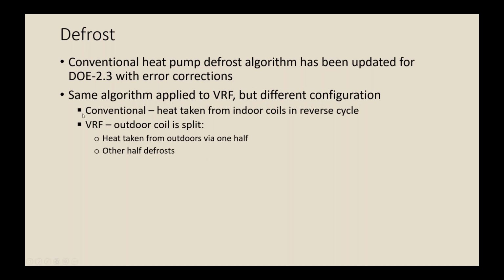In many of the larger, newer VRF systems, there's a configuration where the outdoor coil is split into two separate circuits, and the compressor can operate during defrost where it draws heat from one of the coils and rejects heat to the other coil.